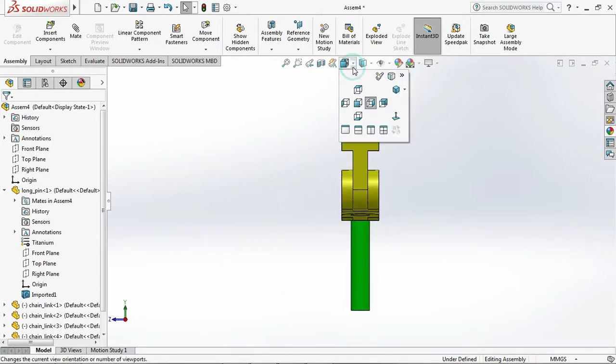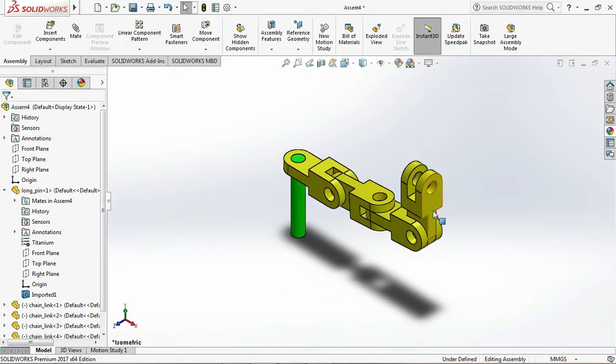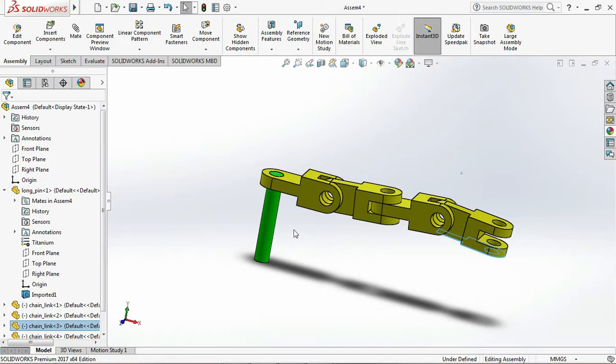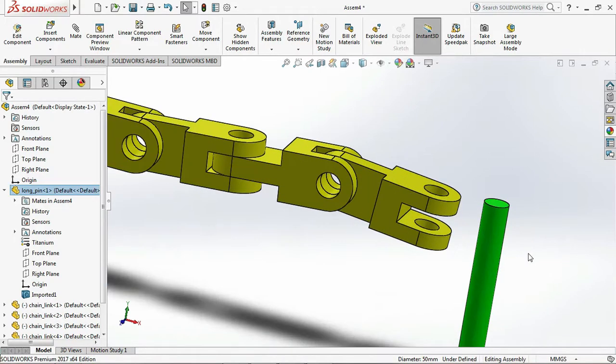No, just want to choose that one. Twist it a little bit so that the other components can be made nicely. So I just want this guy to mate with the final chain link at the end there. So I just hold Control on the keyboard, and then drag like that. Then you get the other component.